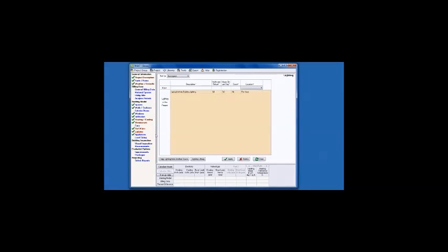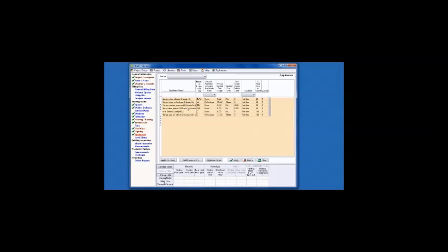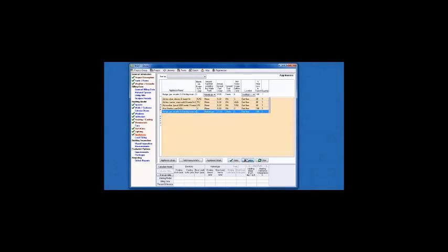Our lighting was defaulted in by the square footage, and that's a setting in your preference file. Appliances are defaulted in by your preference file. The idea being you're not necessarily upgrading your appliances, but you want to have correct internal gains, in other words, all the losses from these various appliances, and making sure your end uses make sense in the end. You want to probably adjust these things. But that's the stuff we'll cover in our training. But at this point, you can press Calculate Model, and you have a fully running calculated base load model.